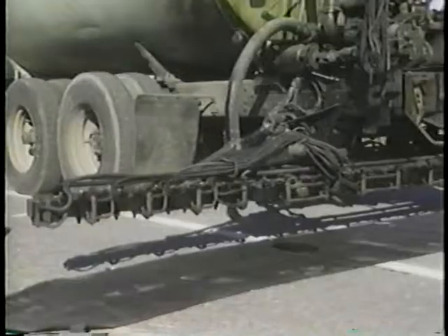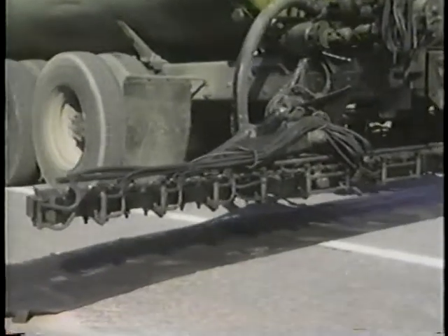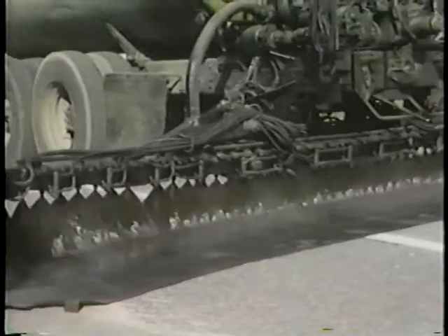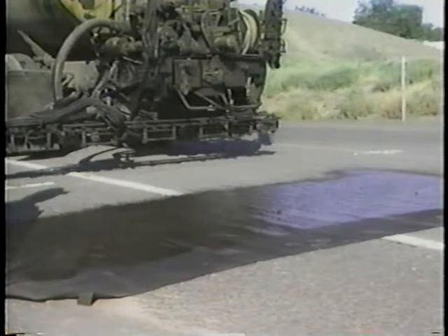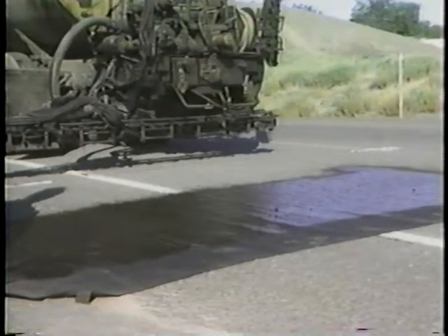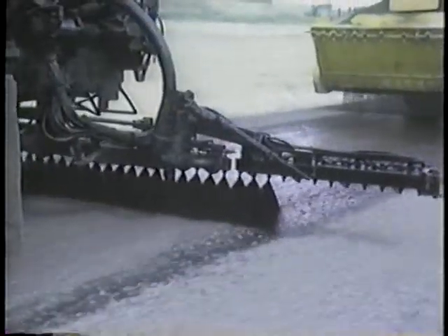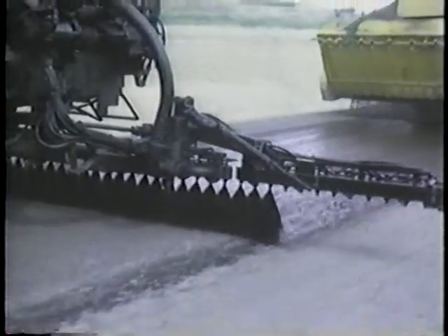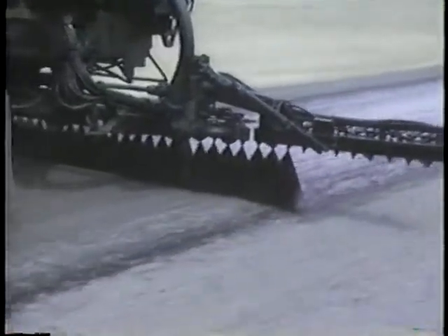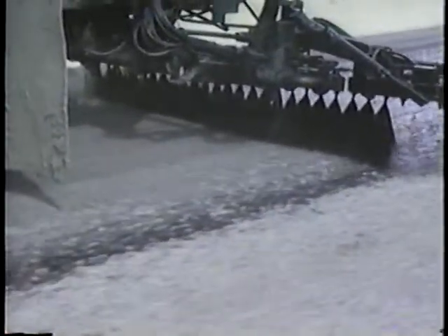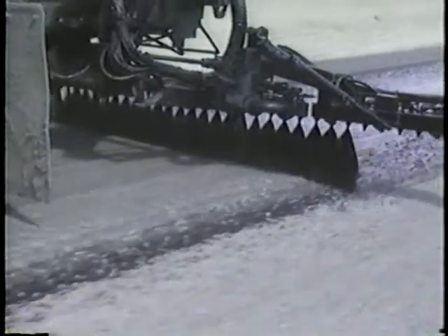If the nozzles aren't angled properly, the spray fans will hit each other and produce an uneven coverage. It's a good idea to check the spray both before the actual application and soon after startup, so that any problems can be corrected before the operation moves too far. Spray bar height also affects proper coverage. By adjusting both the bar height and the nozzles, different spray patterns can be made as shown here. Usually a double or triple lap is used for seal coats.